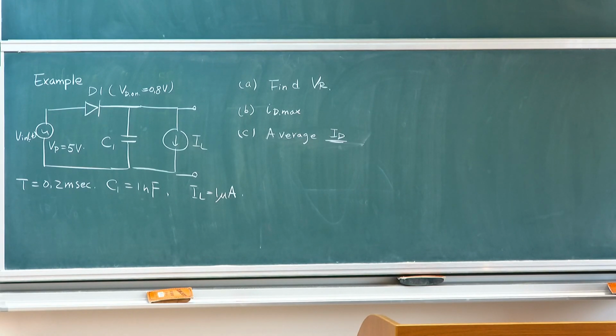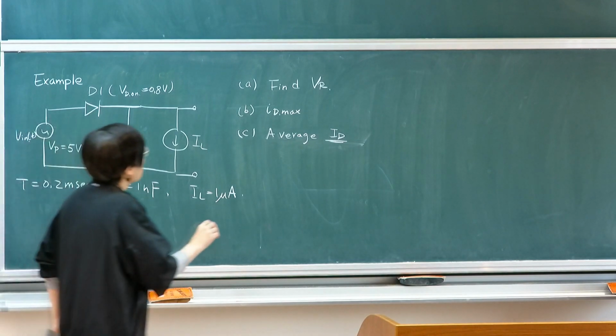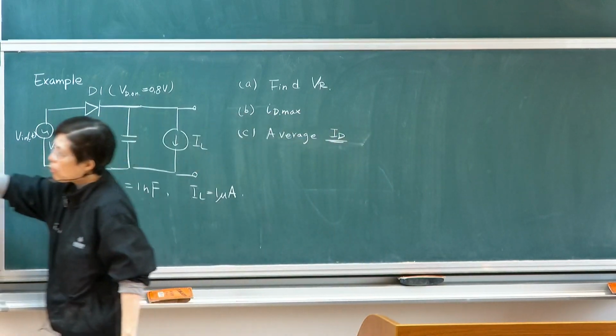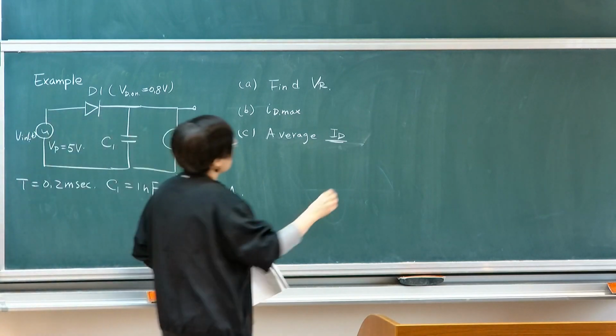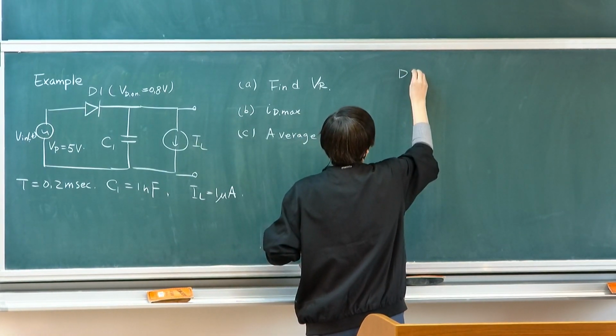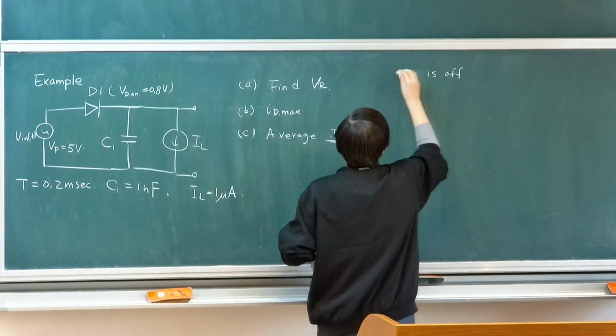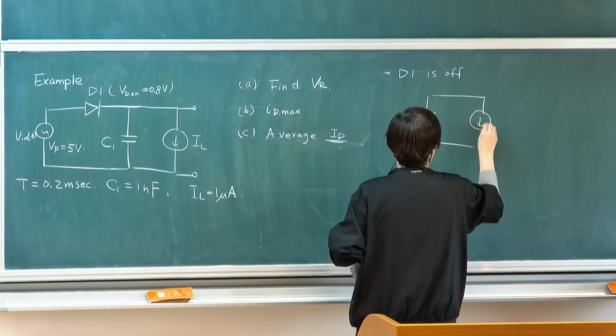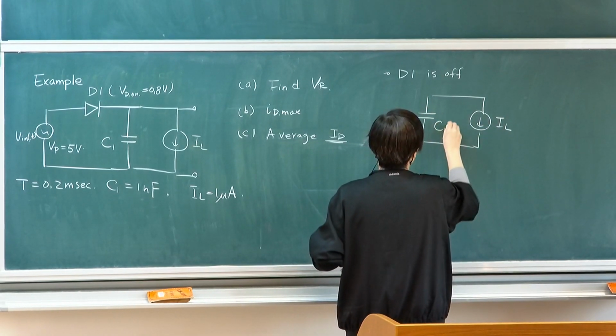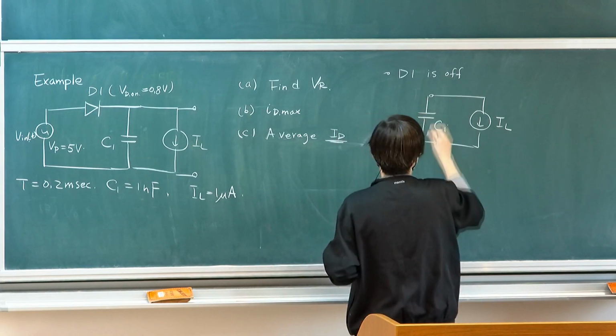It's not suitable for the equation. I don't think I have time to go through it, but I encourage you to try. I'm just going to give a hint as to how one approaches this type of question. First of all, you still want to emphasize what happens in phase 2 when the diode's off, because that determines how much drop there is. So when D1 is off, you draw the circuit. It will look something like this: C1, starting at this T prime point.